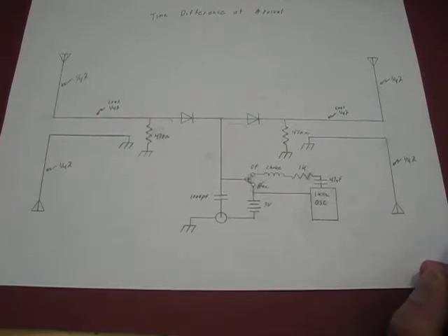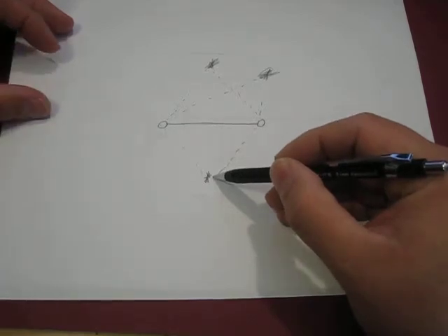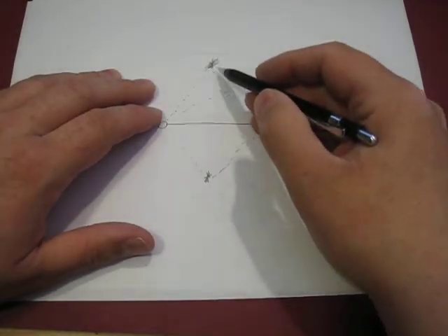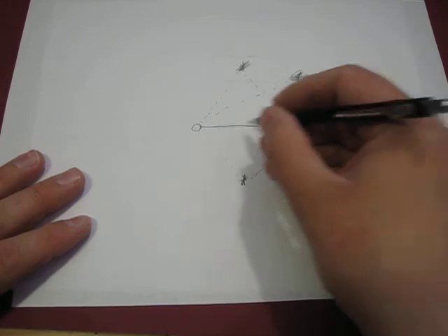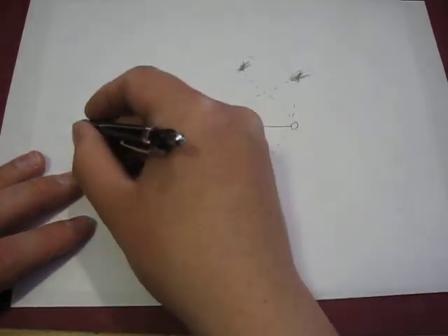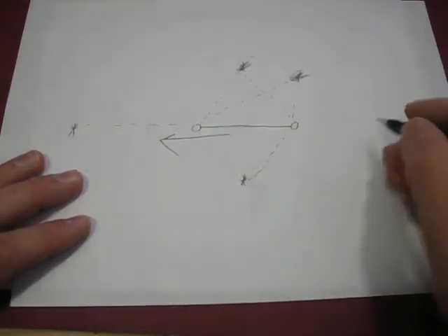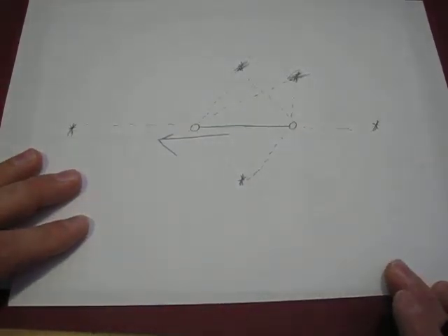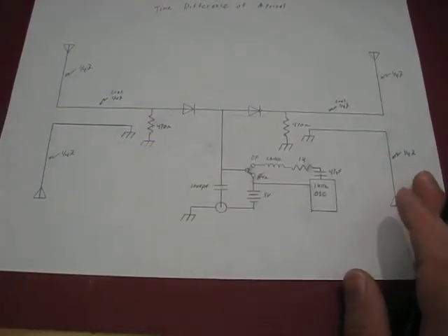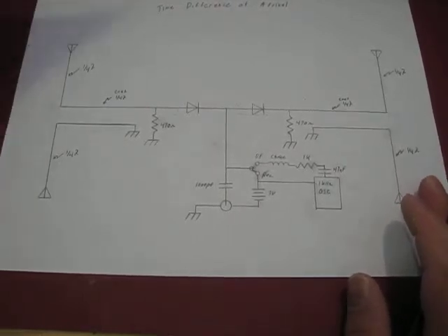And that's how you can determine, go back to this, what direction the transmitter is at. So you can find it this way, then you can switch it to Yagi mode, and when you switch it to Yagi mode, now the direction of travel is this. So when you have your transmitter here, you'll have a maximum signal strength. When you have your transmitter back here, they'll have very little signal strength. And that's pretty interesting. Basically, you can do the two modes with just one little switch and a battery. And basically, that's how this thing works.